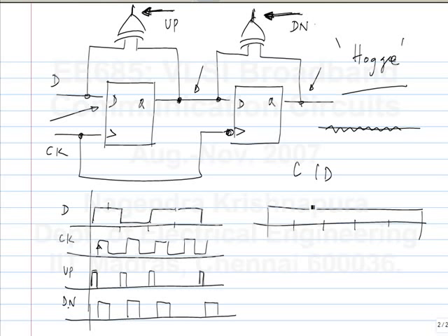So let's say the frequency happens to be slightly higher. At the point where there are no transitions, it will not have any ripples. It will just hold constant at that value. So maybe initially it is here, next it will shift slightly, and it will shift more and more. And if you have a long enough string of identical digits, it can even go to one previous bit. So there is that problem. What does that mean? You have to limit the number of consecutive identical digits. Every clock recovery circuit can be made to fail by having a sufficiently long string of identical digits.